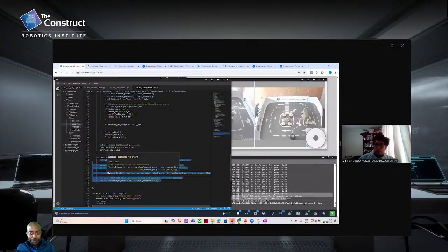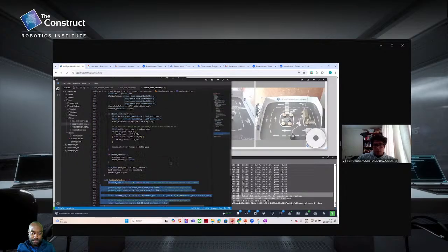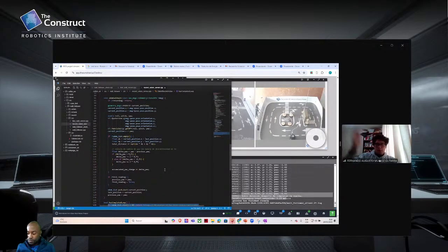The difference of ROS 1 and ROS 2? Some major differences here. Yes, they are very different. First, the commands, because when you compile the program you use catkin_make in ROS 1, but in ROS 2 you have to use colcon build, and there are many commands you have to change. Well, I think ROS 1 is always used to aggregate new programs or new libraries.